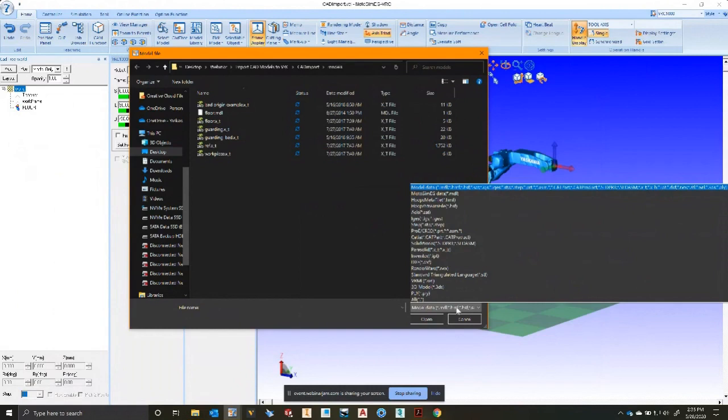What you see on the screen right now, the HSF, is a simplified tessellated geometry. So you can't map a path for the CAM function with tessellated geometry. You have to use actual NURBS geometry, and that's where the SAT file comes in. It does not mean that you should convert every model that you import as a SAT file. If you do that, your sim's going to be huge. SAT files can be 10 times larger than HSF.